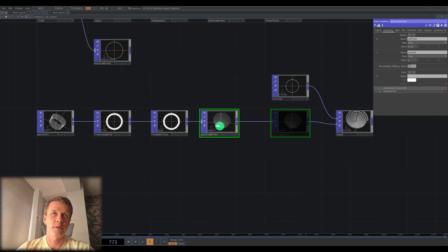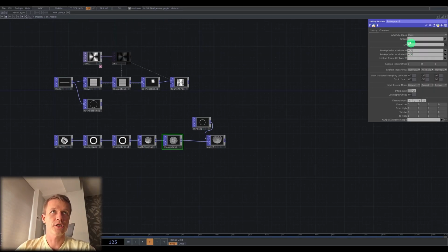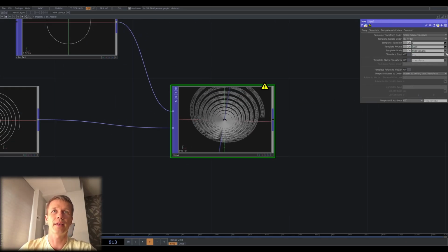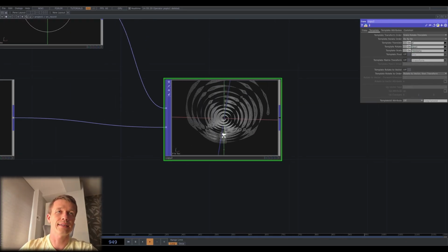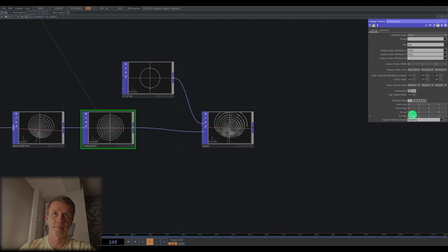Okay, we can also bring the texture control into this spiral the same way. Again, I use the same texture, and let me call it, I don't know, text data, because I could use this text data for any attributes. But now I will use it as a scale attribute in copy pop, and this changes the size of the copies along the spiral.